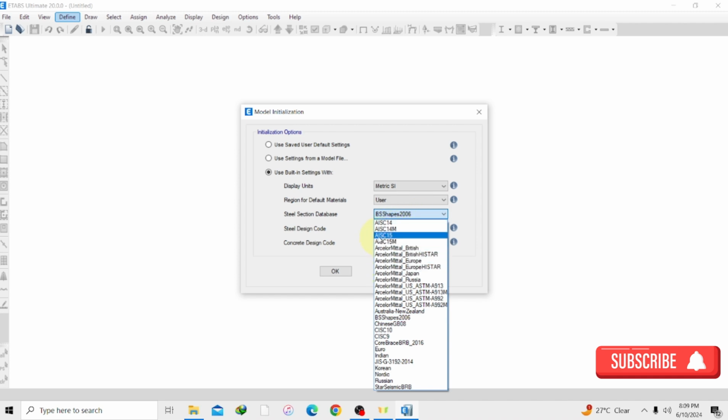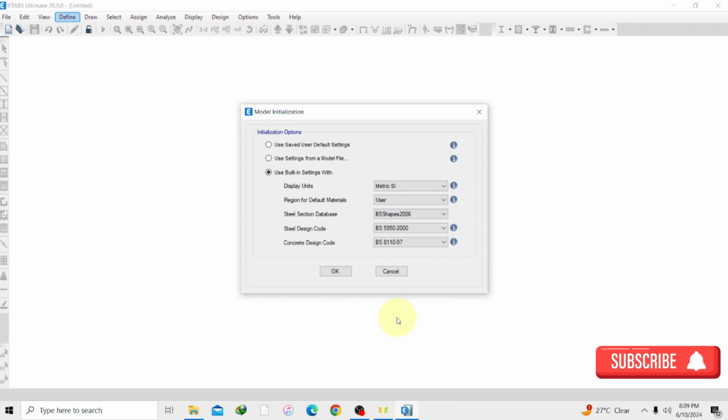We have the AISC 15, we have the BS shapes, we have the Indian code, we have the Korean. So based on the code you are using, you just select any of them. Since I'm using my BS code, I'm going to select the BS shapes 2006. And we have our steel design code here, where the code you are using to design your steel.